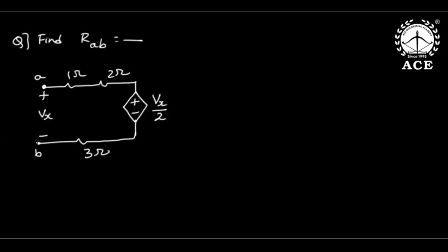Now listen. In this problem, there is a dependent source. Unlike an independent source, you cannot remove it here. For an independent source, by the passive property, a voltage source is shorted and a current source is opened. But this is a dependent source. A dependent source will have some internal sub-circuit resistance, so we should include that now. In this case, again, reduction is not possible.